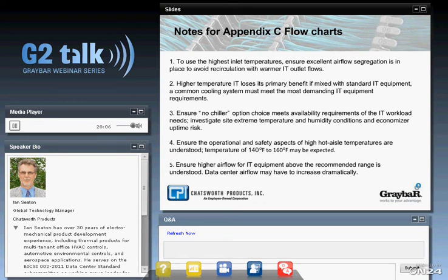And then finally, we want to keep in mind that as we raise the temperatures, the server temperature sensing is going to respond to that, and there'll be at some point where we're going to be consuming more air through those servers, which means our air delivery system into the data center is going to need to ramp up accordingly. So there's basically a twofer there, a double whammy, when we start paying those fan penalties. And we'll talk a little more detail about that in a subsequent slide.